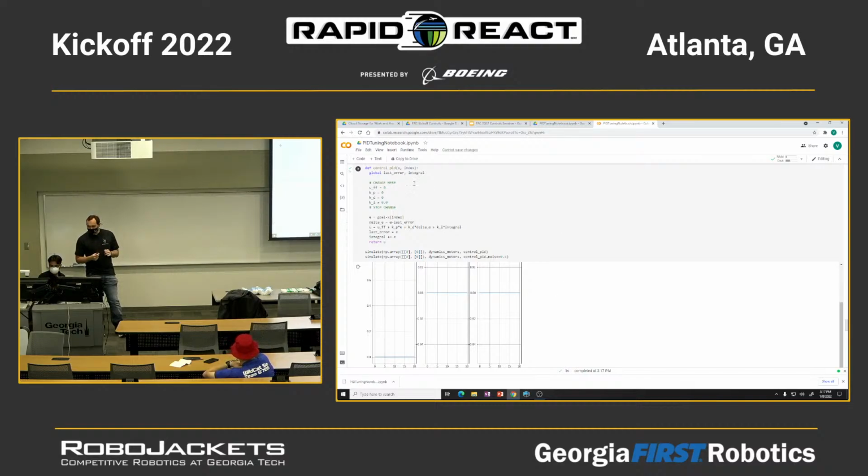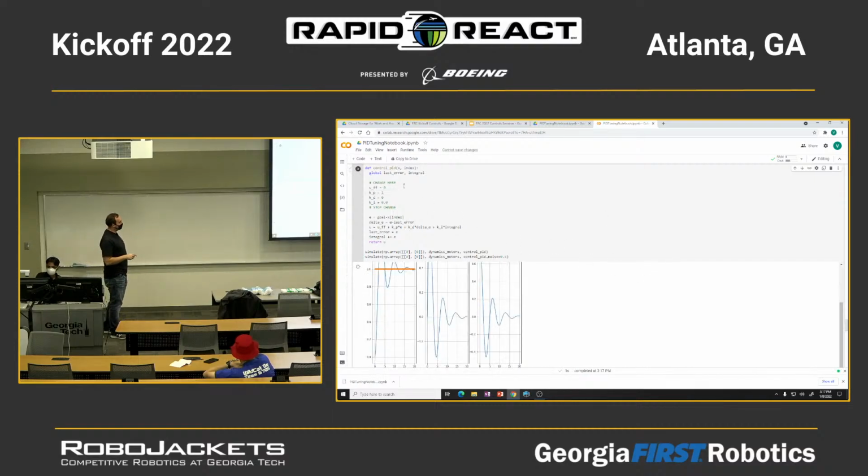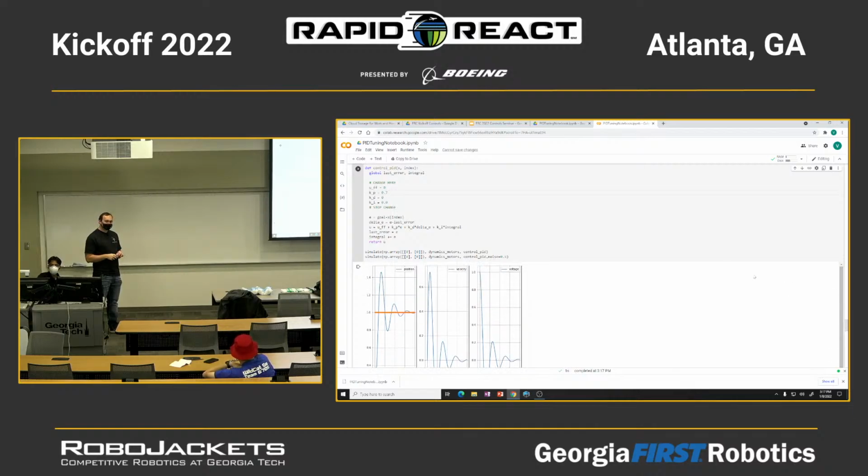Yeah. So the way you'd usually tune the PID is you want to set P to a number. Start off with just P, so everything else to 0 and then just set P. And what you want to see is that you quickly reach your set point. That's kind of what we're seeing here. So in this graph, if you want to go to position 1, you see the robot's going to get a 1.4, right? What happens if there's a wall at 1.2?